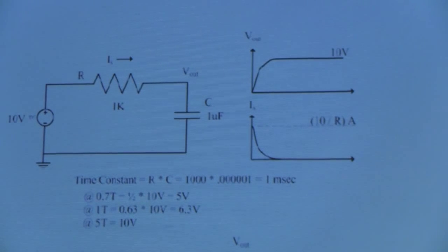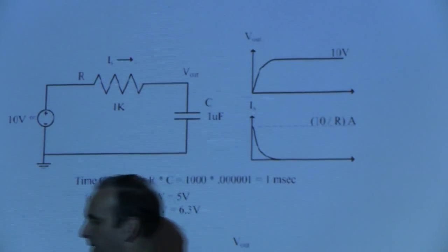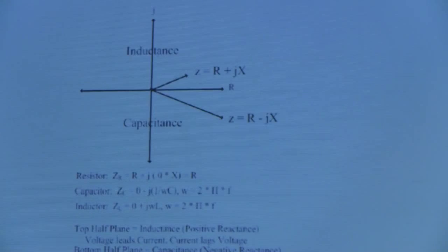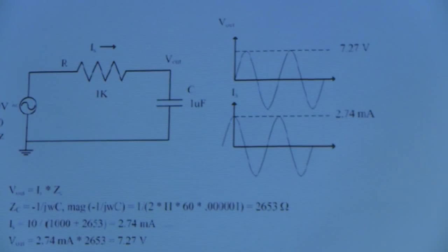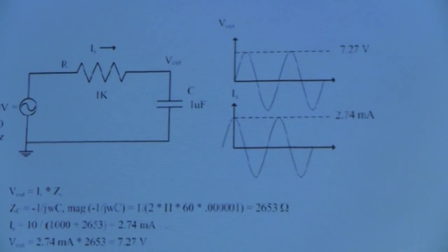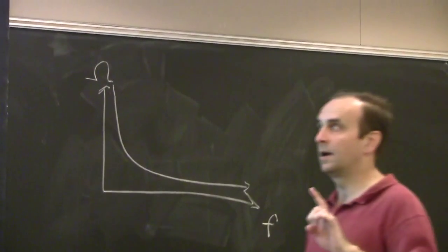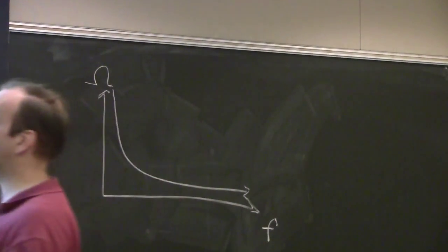Now, because of the math, the impedance of a capacitor is 1 over j omega c. So right there, the impedance falls off. So at some frequency, in effect, this capacitor should be 0, it should be a short circuit. Now, I'm going to tell you why that's not true, but for the minute, pretend that's true.